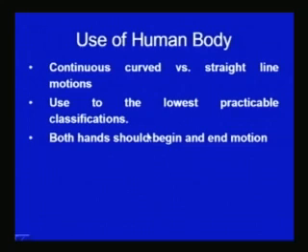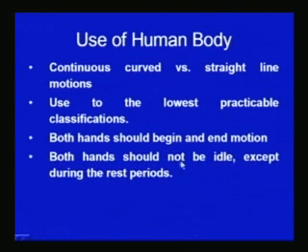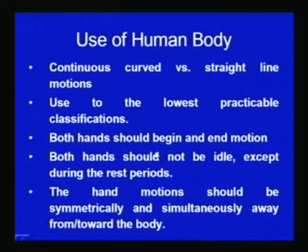simultaneously. The work methodology should be designed in such a way that both the hands remain busy and they should start and end their motions simultaneously, and both the hands should not be idle except during the rest periods. The methodology should be such that the hands remain engaged and both hands should not be idle in any case except when the worker is resting to recover his muscles and overcome the fatigue.